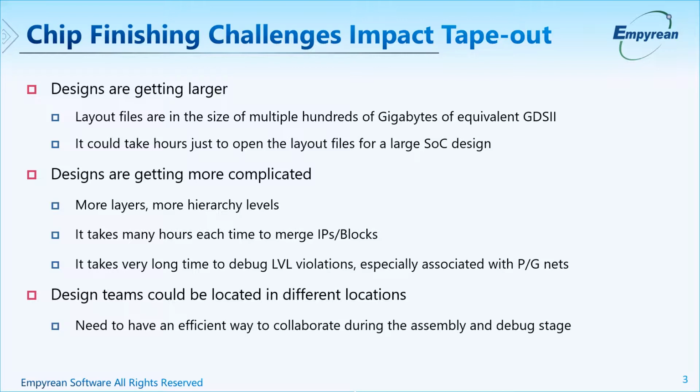All these are posing huge challenges to the engineers using traditional chip finishing tools. It could take hours just to open a large design layout, not to mention if you need to debug any LVS violations that involve PG nets.